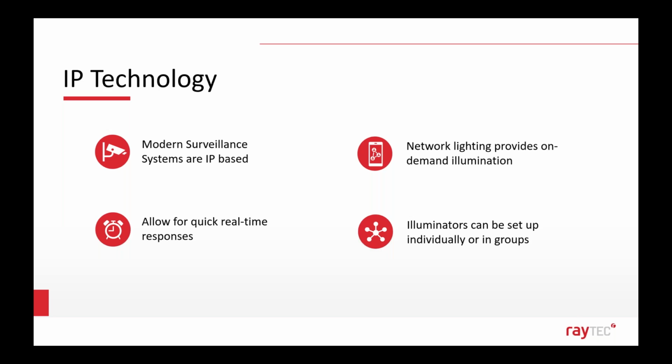Or importantly, especially for applications where lamps are very tricky to access, so again, on a gantry overhanging a fast-moving road, for example, you can remotely access diagnostics and the status of the light. So IP lamps are definitely another string to your bow.